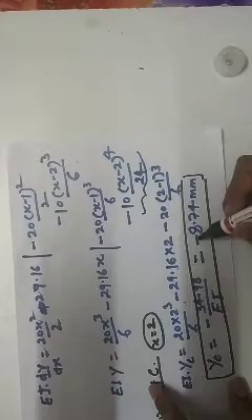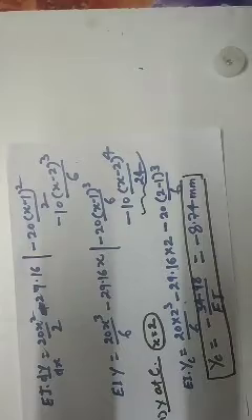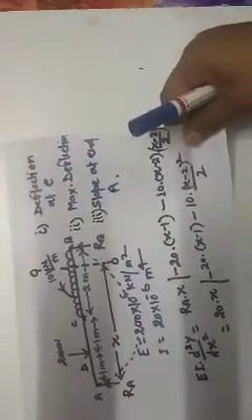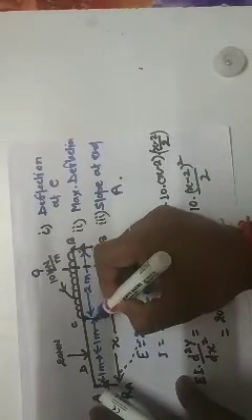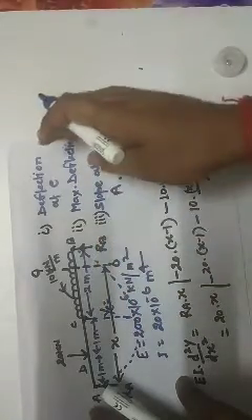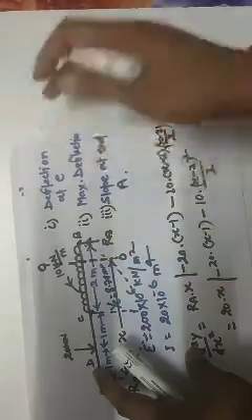The minus sign indicates that the deflection is measured on the negative y-axis, right? It is measured at the negative y-axis. So how will we mention it? This is the point C, right? Then the deflection at this point is yC, and it is equal to 8.74 mm, downward.